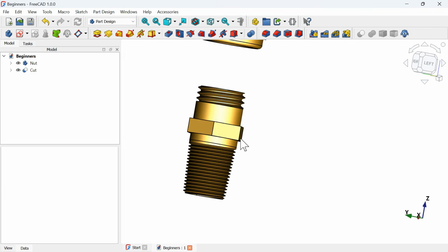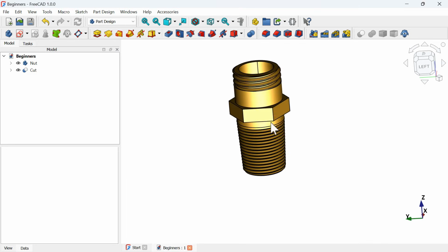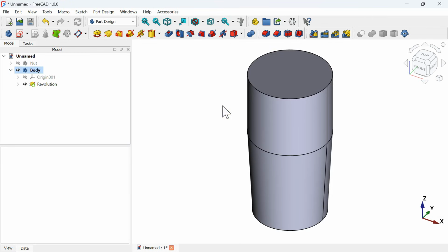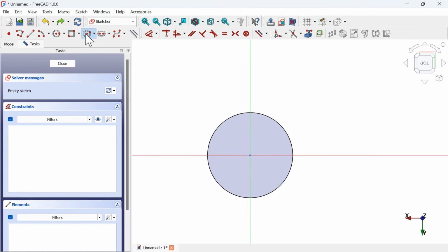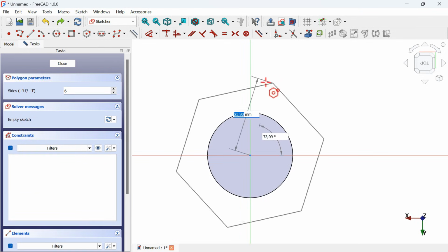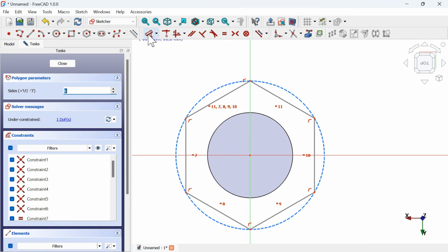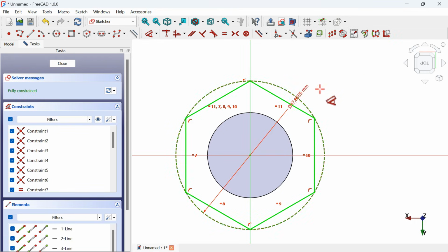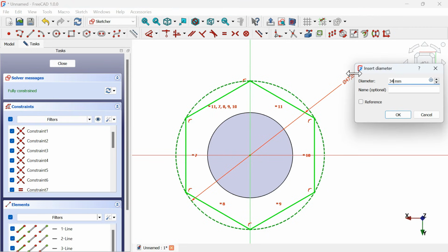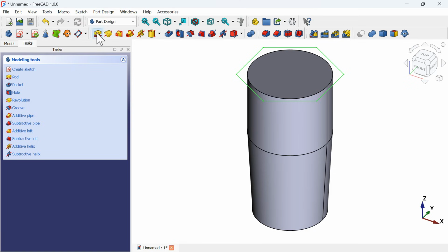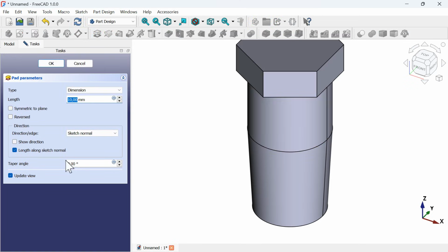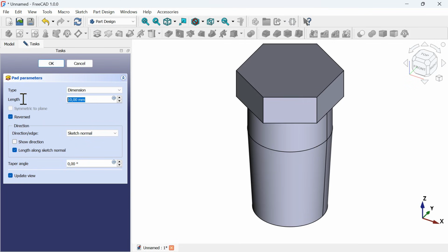The next thing that we'll do is to create this shape here. To create this shape, we'll need a sketch first. So let's do that. Go to our document, select this face here and create a sketch. Select this geometry here, and now click on the origin axis and create this geometry. Now use the dimension tool and click on the circle and set a diameter of 34 millimeters. Now escape 2 times to leave the sketch, and next use the pad tool to create an extrusion of this sketch. Set reverse it here and set a length of 8 millimeters, and here I have this.